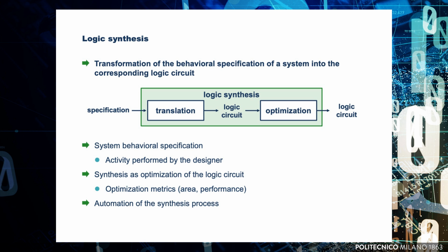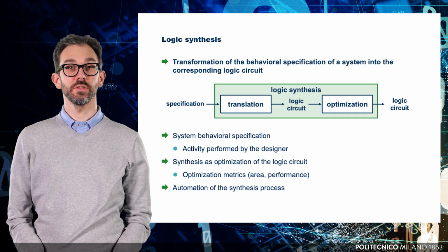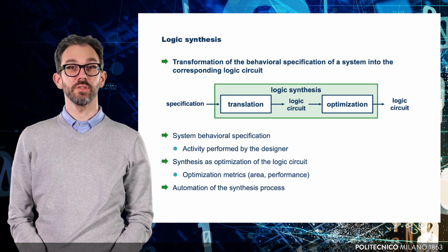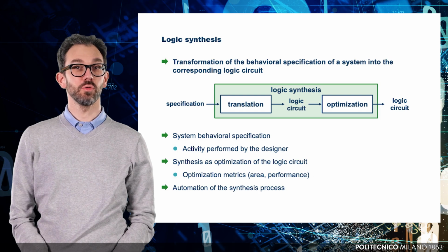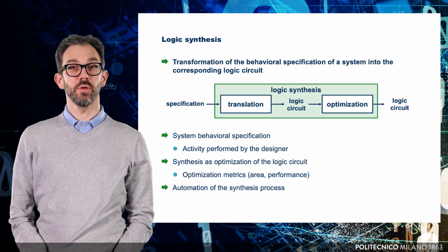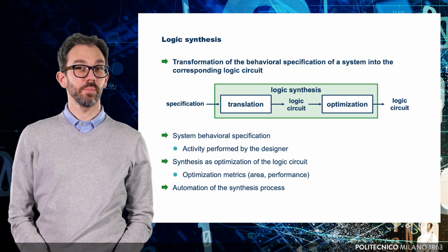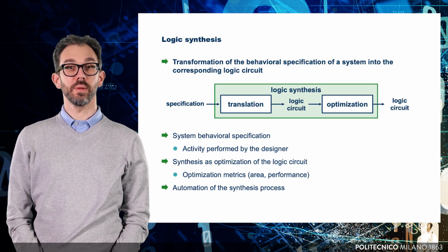As we will see, the number of logic circuits that can implement a given specification is, from a theoretical point of view, infinite. The goal of logic synthesis is not only to translate the specification into a circuit, but also to identify the most convenient implementation according to a set of non-functional design requirements, such as maximizing performance or minimizing the size of the system to be implemented on the chip.